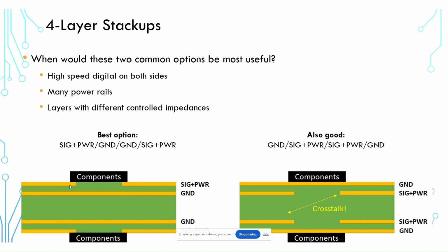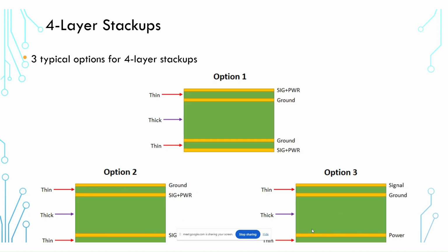Here, it requires you to route power as large rails or as traces. And that's perfectly appropriate, even in systems where you have a big processor. The power demands for some components can be high, but it's not so high that you necessarily need to have a power plane. And in fact, in this type of system with option 3, one of the reasons that you might use a power plane is because it gives you some convenience for getting power over to the components up here on the top layer, without having to route any dedicated power traces.